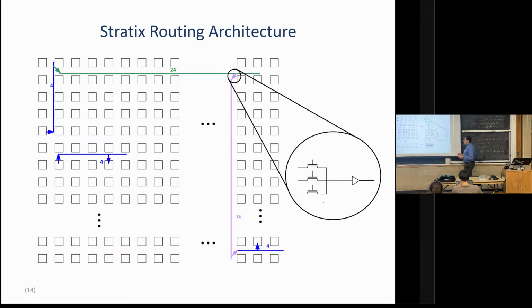I guess it doesn't strictly necessitate it, but as you start getting expensive resources like these long wires, it becomes kind of desirable to make it easier to get on them. So you might go, well, I'm going to have a few muxes, and those muxes don't directly drive a wire. They just drive another mux that drives a wire. And essentially, it's a way to get more options of how do I get onto this expensive resource. So you don't have to do that just because you have long wires, but having an expensive resource like long wires does make them more desirable.